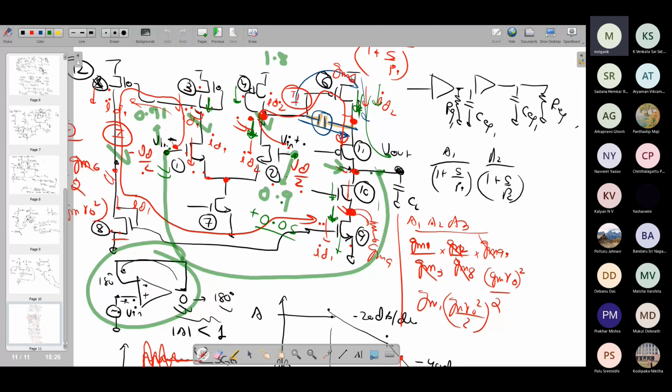Your two inputs are always going to be exactly the same. Why does it happen? Because of this gain. The larger the gain, the closer these two voltages will be. Because of this small signal operation and the changes in the small signal current, the negative terminal voltage will eventually follow the positive terminal voltage, and hence the output voltage will follow the input voltage.